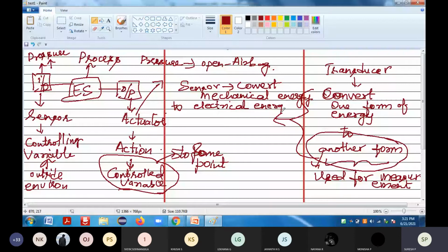You can see it here. If it is for 1, B and C are on. You can see it from the figure. If 1 is there, B and C will be on. B and C on means the hexadecimal code is 06H. Similarly, if I want 3, for 3, A, B, G, C, D.